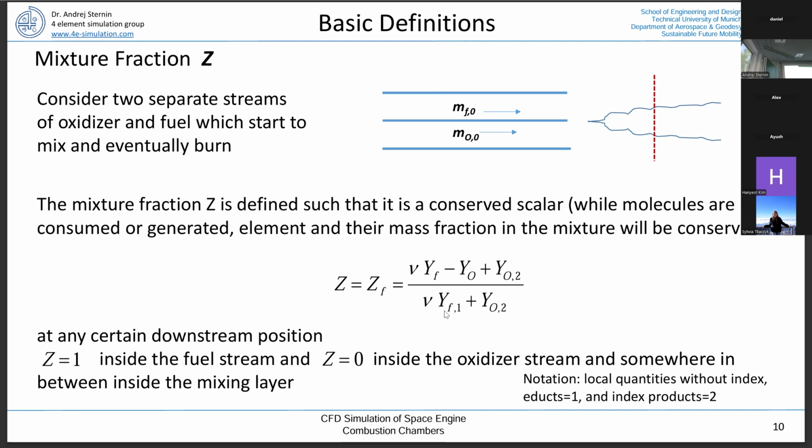And that's, for instance, also violating what we know, the Kolmogorov hypothesis, that we have a certain decay of turbulence. This is not the case in most of the combustion processes. So we have a violation of that Kolmogorov hypothesis due to the fact that if we look in detail, we see that there might be turbulence generation due to reaction. Later on, if the temperature is high enough, then viscosity is overcoming, and then we get better.